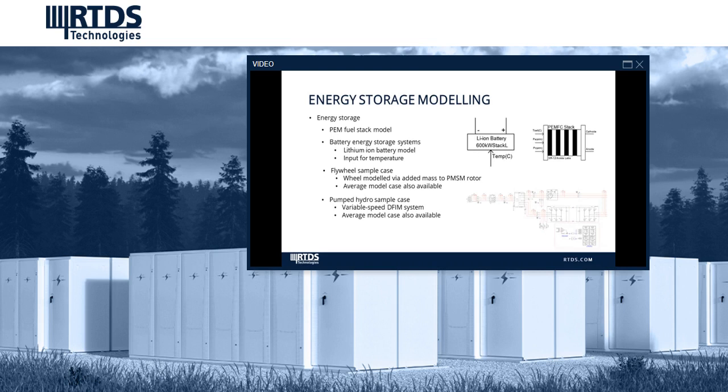We do accept temperature as an input and use interpolation to calculate the internal parameters according to the temperature and state of charge. We have mechanical energy storage modeling options as well, namely flywheel and pumped hydro storage, and RSCAD comes with fully documented sample cases for both of those, including the controls and of course the power electronics modeling.